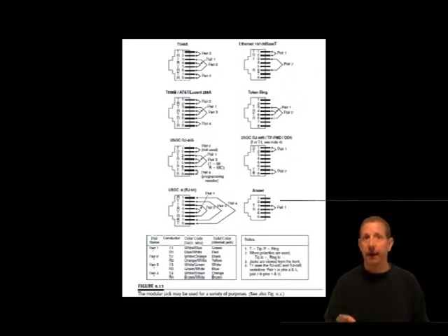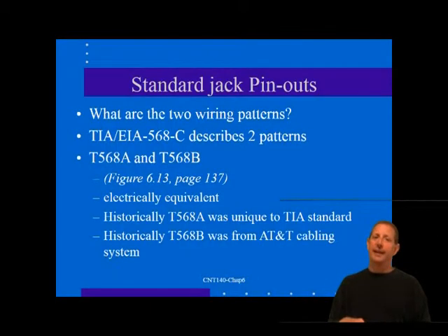The 568A pattern places pair 2 on pins 3 and 6, and pair 3 on pins 1 and 2. So basically, what we're doing here is switching the green and the orange pairs. Okay. Now the 568B pattern, okay, covered that.